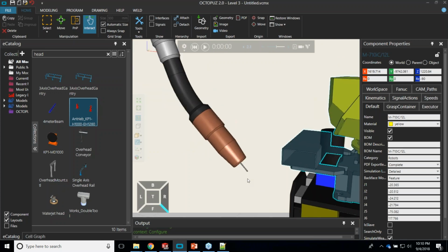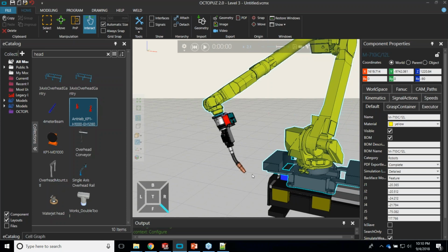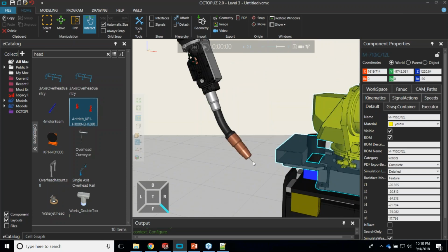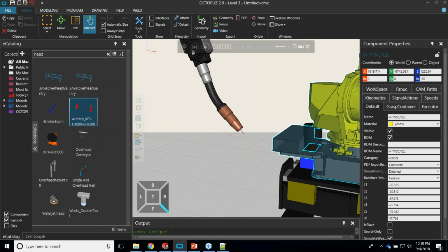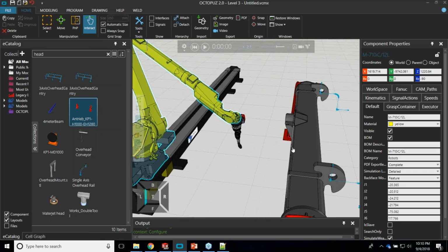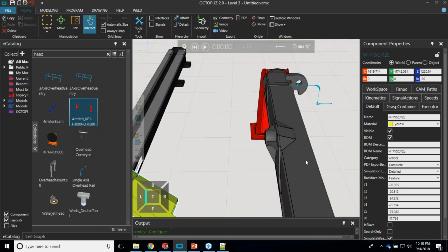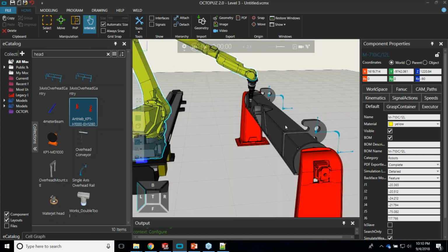The way you teach a TCP depends on the brand. I taught a TCP as part of a training here last week on a KUKA, and on that KUKA, you have to teach at least 4 unique orientations of the tooltip at a specific point. You want something that's going to come to a tip on your part. It doesn't really matter what it is, but you're teaching some point in space 4 times in 4 different unique orientations.